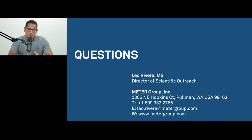Ideally, if you're really trying to quantify, to really get down to the horizon impact, and we just had this discussion with some folks at the NRCS, the best thing to do is excavate down to those different layers and make measurements at the different layers. You can do that with a tool like the SATURO, or you can use other tools like a borehole method, or you can take core samples from those different horizons. Again, each of these approaches is going to have challenges.